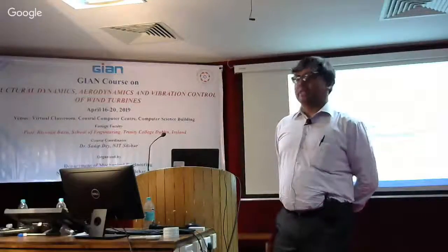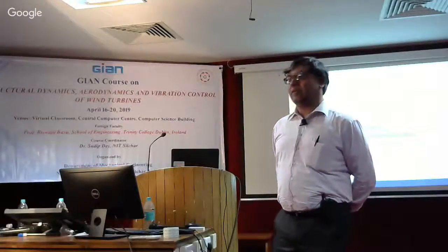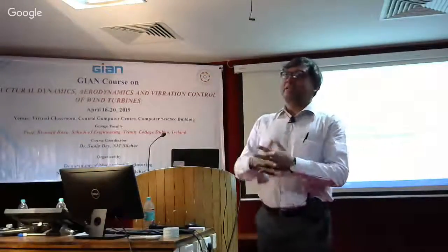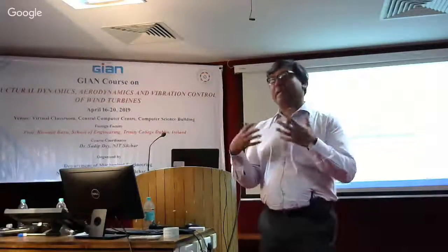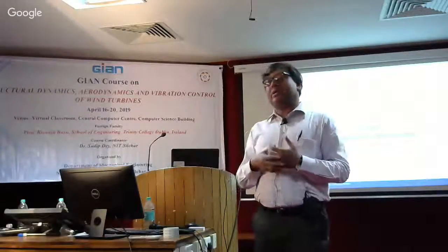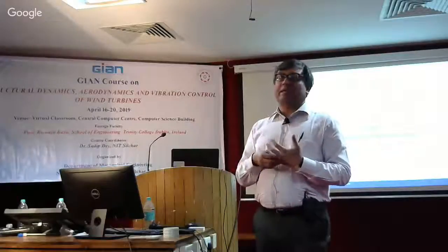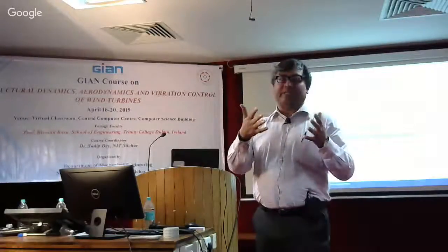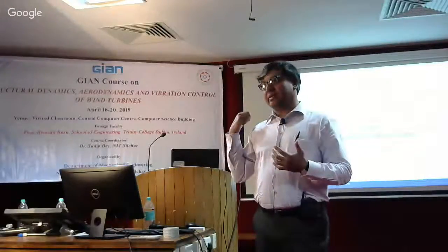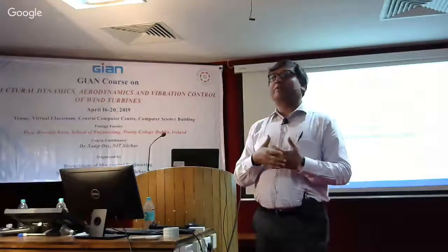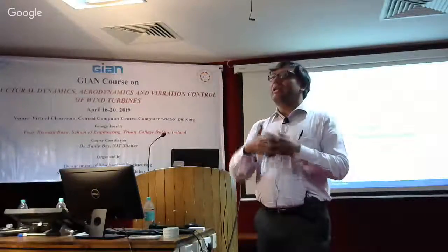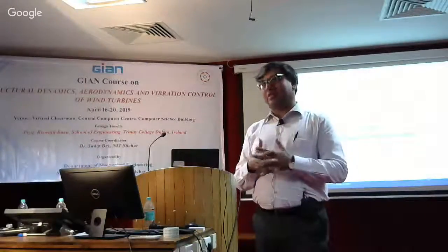I mean, two reasons here. One is just for the sake of convenience, also we decouple because it's easier to design a single input, single output system. We understand the dynamics much better, and then we can go back to the original system. Now, if you look at this system, obviously, a lot of the systems we have discussed so far are time variant, but linear. But you may also have non-linearity here with the current systems, aerodynamic load and so on. So the decoupling may not be easy because then you have to linearize in some way and then decouple.